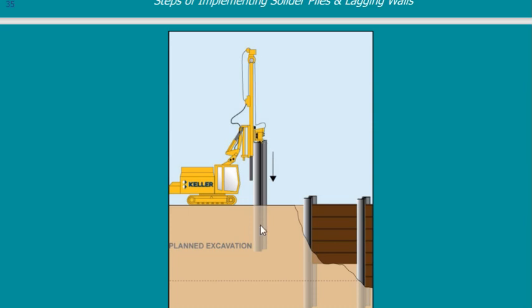So I drill here till I reach the depth I need, and then I go to this, and then to this, and this. So I finish the whole site all around with holes. And once I finish the hole, I insert a steel section, maybe an I section. You know, instead of C or Z, there is something called an I section.